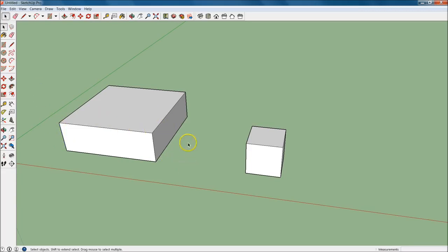But if I wanted to just have a little bit in there, if I start from the bottom right and move up, you'll see that my box is this dash line. The marquee is this dash line. And what that'll do is select everything that any piece of that component or part touches. So if I let go right here, you'll see that this surface was fully selected even though the whole surface wasn't within that marquee. Also, these lines coming out right here weren't fully in the marquee, but it still selected them because part of them was in there.